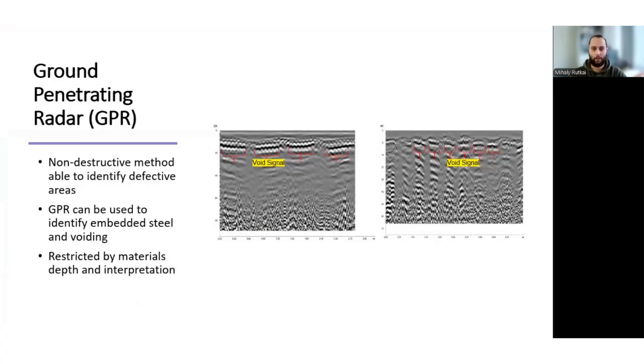Now, ground penetrating radar devices are a quick, easy, non-destructive way to inspect structural elements. These devices are often used to locate reinforcement within the concrete, but are also useful in identifying areas of delamination or major voiding within an element. When there is sufficient voiding, the signal will be reflected and be visible on the digital display.